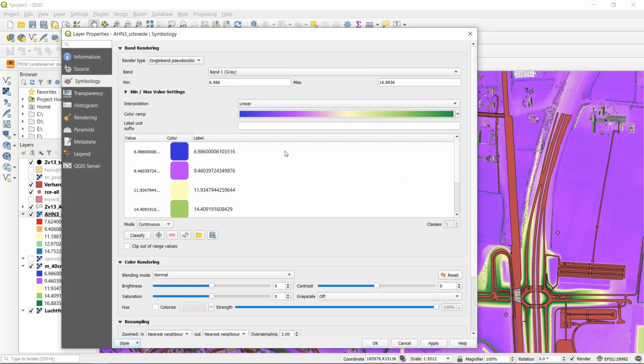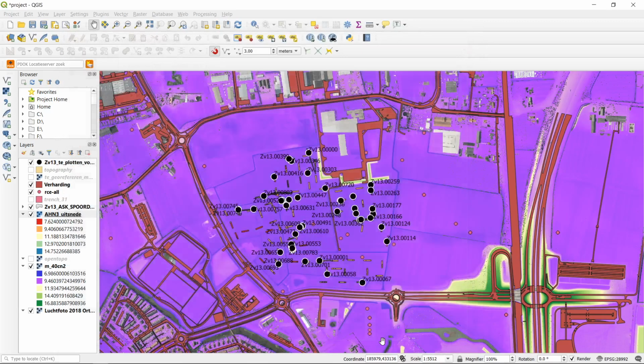Now what happens is we have now suddenly the values of the LiDAR sheet again. We have the selected color ramp, and if we would have set other options, that would also be imported onto this layer. Click OK. And here we are back with the visualization, which is a direct copy in all aspects of the downloaded LiDAR sheet.